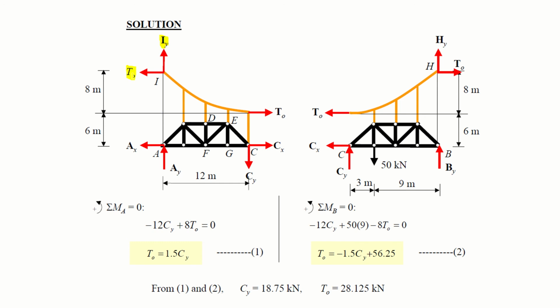Similarly, this is tension in cable. Similarly, at H there will be a vertical component and horizontal component, which will be the tension in the cable. Similarly, at the middle there will be a tension in the cable, right? And at point C or the point right above point C, the tension will be the same, T naught.